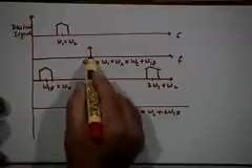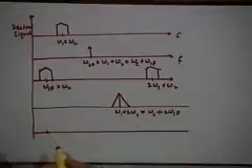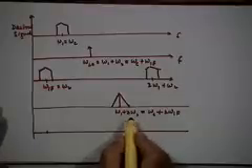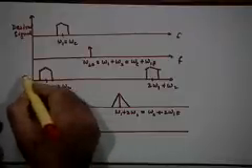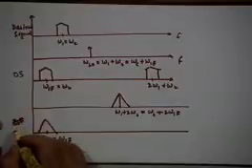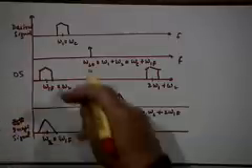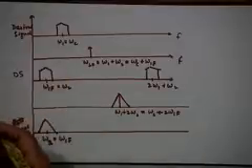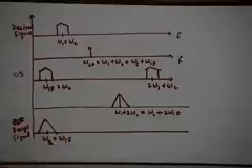When this mixes with this local oscillator, what will this produce? It will again produce an output which is centered at omega 2. So, we will get this signal at omega 2, which is at omega IF. So, this is the desired signal and this is the image frequency signal. And these two things are coming together into the IF amplifier, because the IF amplifier will see this spectrum as well as this spectrum at the input. So, both the signals will go in and now you will have a problem. There is no frequency selectivity.